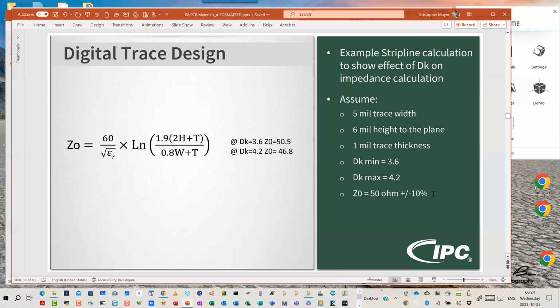So for the breakout, I kind of was loose with that, but for the main track, it was smaller than 5 mils for sure. And that's where you're running into the problem. As you get smaller and smaller in trace width, the fabrication tolerance on the ability to etch that trace to exactly that width becomes a greater percentage of that width, which is causing that greater variance in Z0.